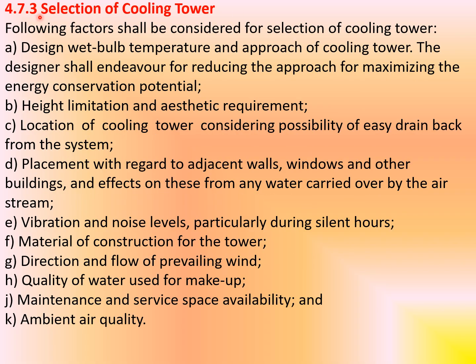Now we'll discuss, friends, selection of cooling tower. The following factors shall be considered for selection of cooling tower. A. Design wet bulb temperature and approach of the cooling tower are already defined. The designer shall endeavor to reduce the approach for maximizing the energy conservation potential.